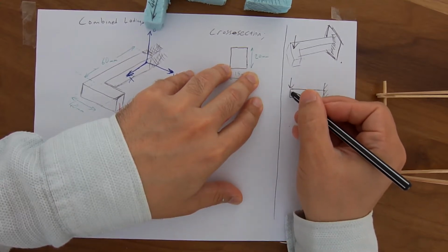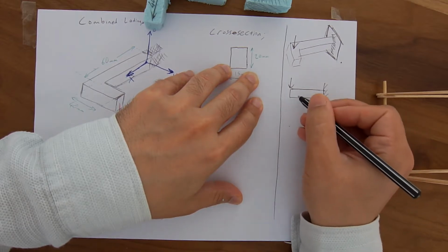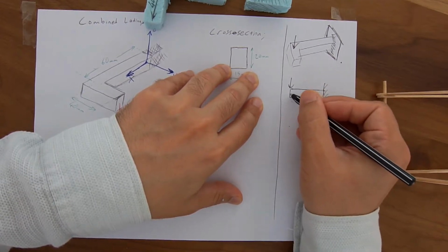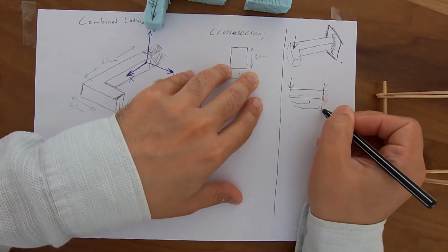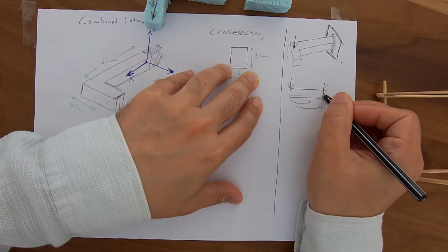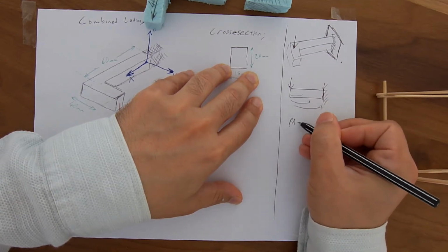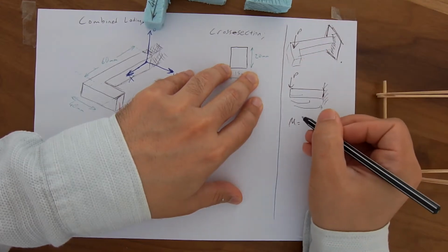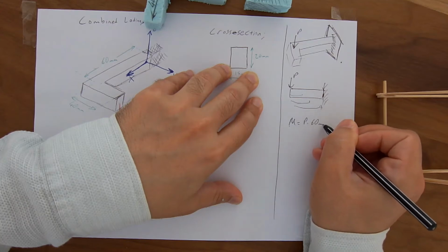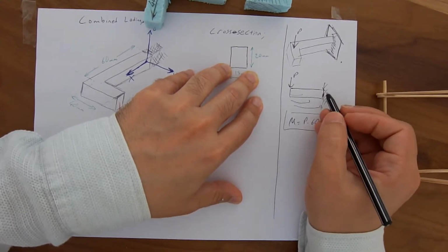So we have zero moment around where the load is applied, and maximum moment here, because the force is the same. If we multiply it by the larger force distance, we get the larger moment. Therefore the largest moment is where the largest force arm is. It is here. So if the load is P, M is equal to P times the force arm, which is 60 mm. So it failed here.